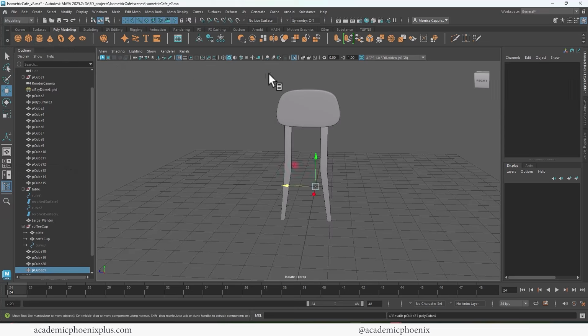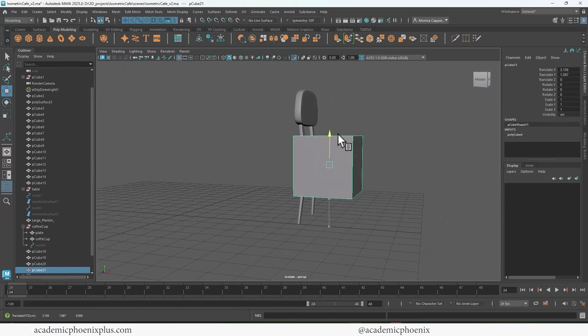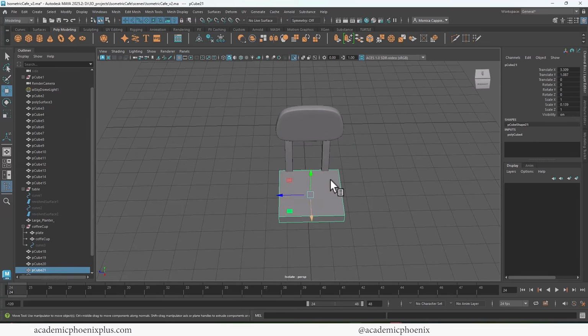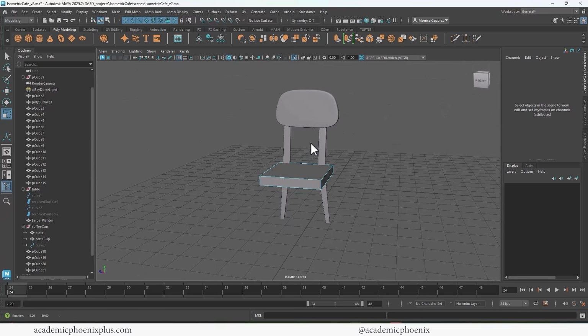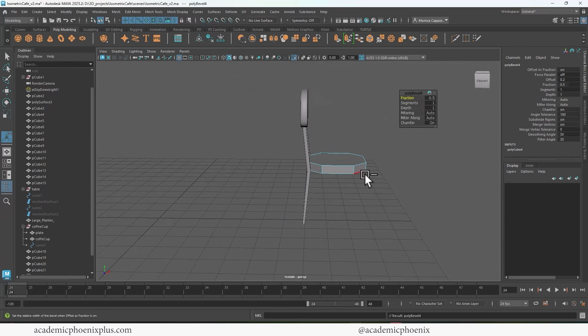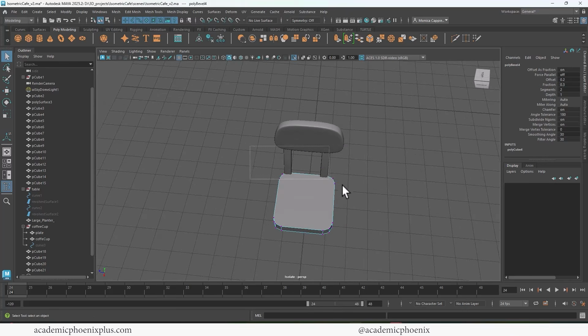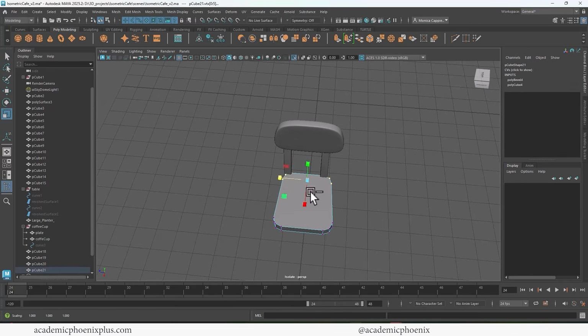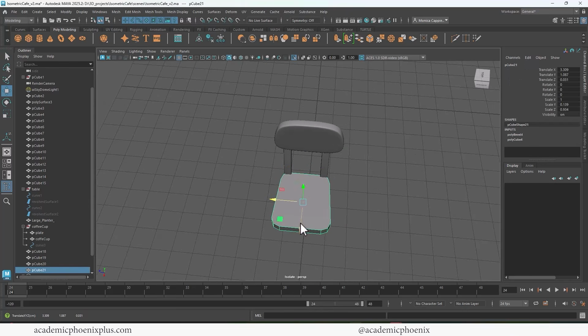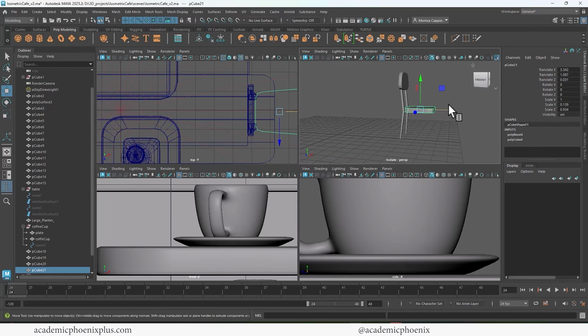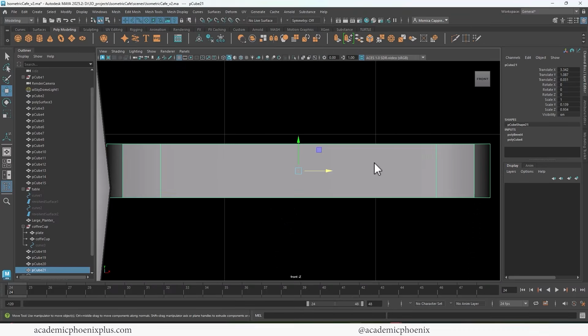So we're going to bring in a cube. And like the other soft edges, let's go ahead and select these guys, do a Control B, increase our segments, maybe change the fraction a little bit, type it in, maybe a 0.3. I'm going to grab these vertices here and just scale it in a little bit. Move it in place, and just like everything else, I'm going to go to the side view.